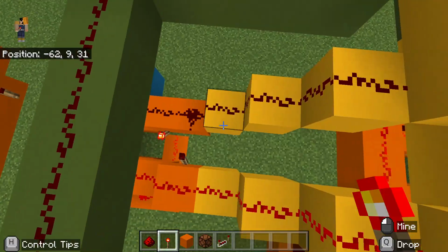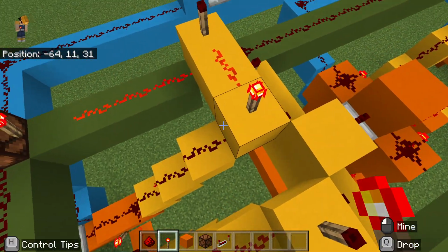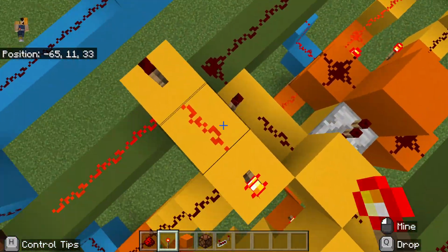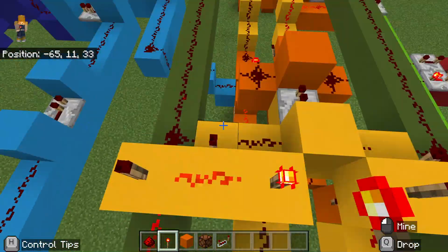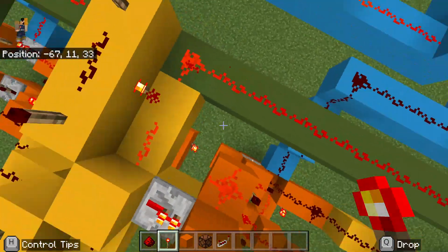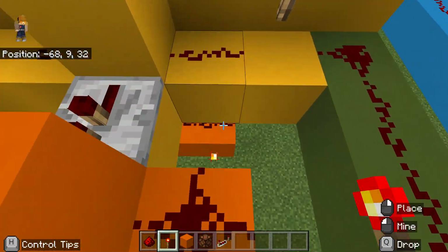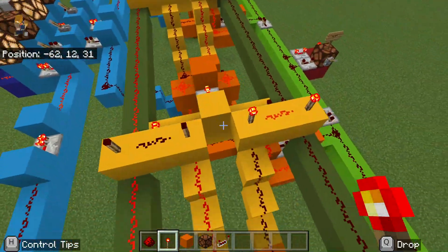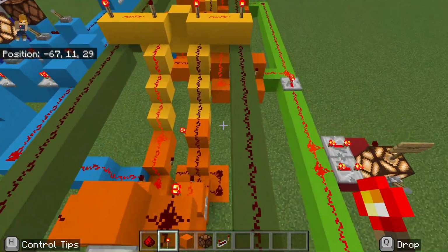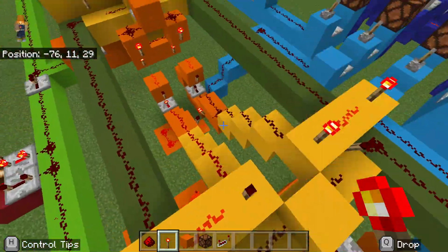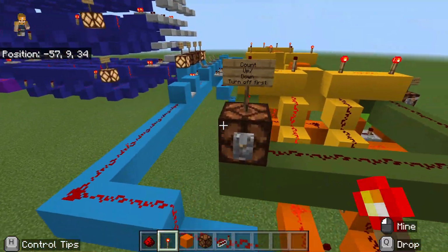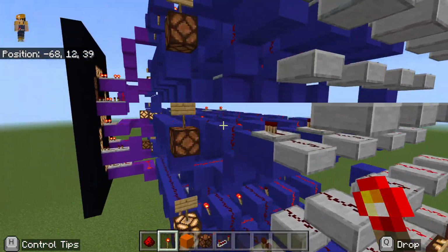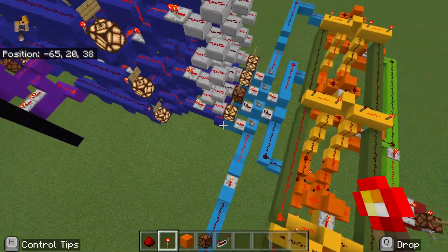Right now it's counting up, and all this is doing is taking our Q or Q bar output and ANDing it with this wire or that wire. So if we want to count up, we will use this side, and that will mean that it'll toggle whenever Q is high, or if we want to count down, it'll toggle whenever Q bar is high. I'll show you that now. Actually, I'll do that later, because we can go on to here.